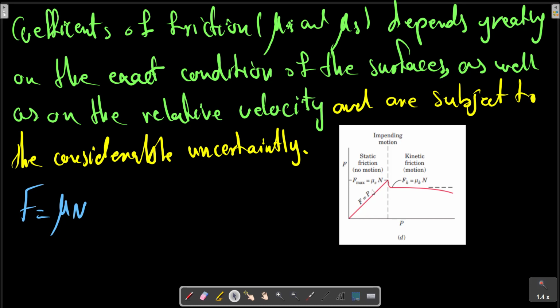Rougher surfaces are more likely to have a larger angle between the reaction and the normal direction than smoother surfaces. Thus, for a pair of mating surfaces, a friction coefficient reflects the roughness, which is a geometric property of the surface. With this geometric model of friction, we describe mating surfaces as smooth when the friction force they can support is negligibly small. It is meaningless to speak of a coefficient of friction for a single surface. Friction angles.